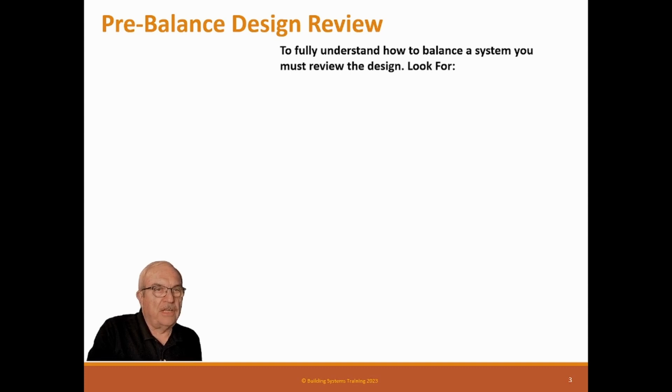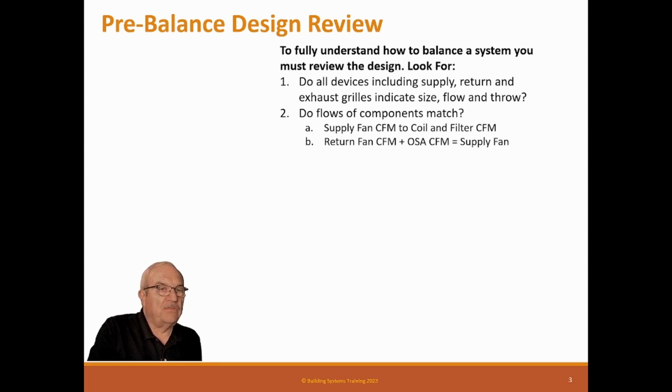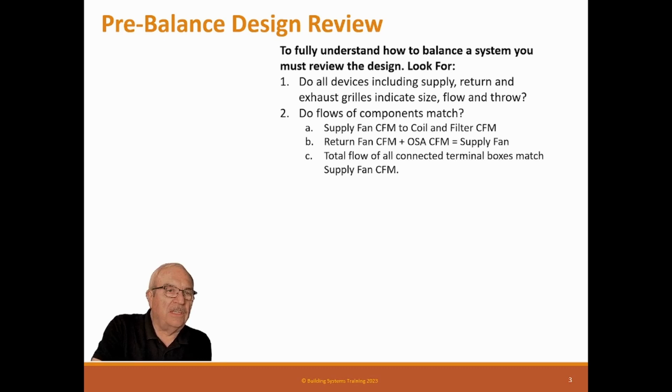So to fully understand how to balance a system, you must review the design. Look for: do all devices, including supply, return, and exhaust grills, indicate size, flow, and throw? If not, you actually need that information to balance. You're going to have to ask the engineer if that data is missing. Do flows of components match? Do the supply fan CFM, the coil, and the filter CFMs all match? Do the return fan CFM and outside air CFM equal the supply fan CFM? Does the total flow of all connected terminal units match the supply fan CFM?